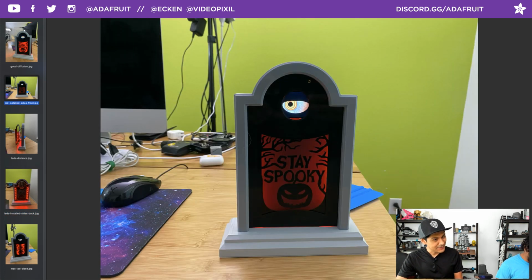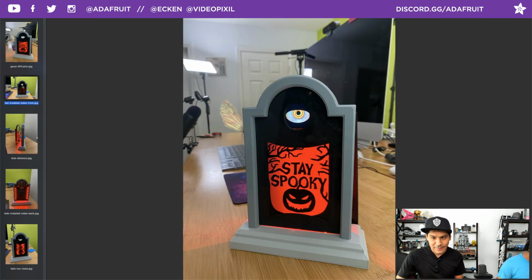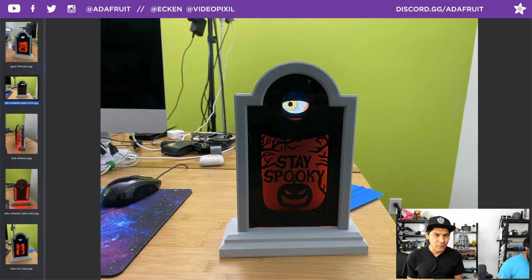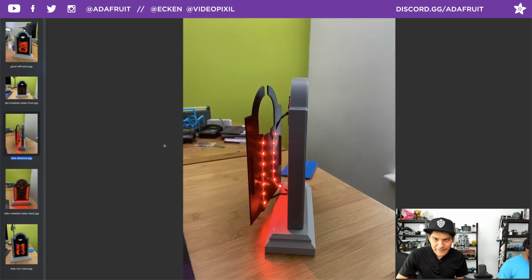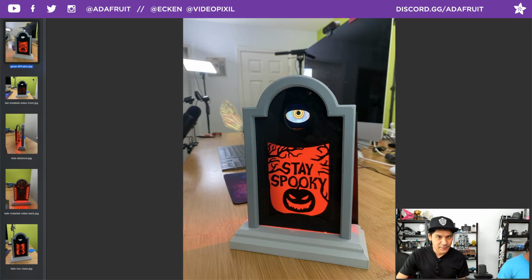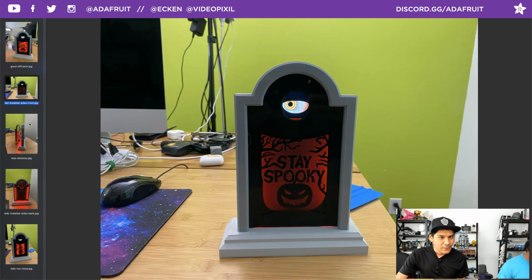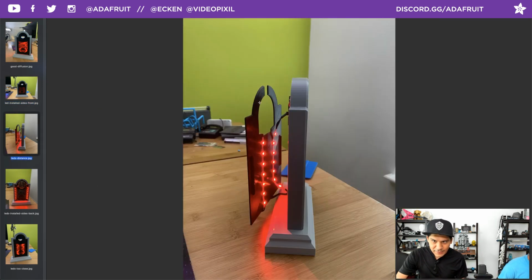It's very, very dim. That is an okay effect, but when you look at this and then at this, it's not an angle or camera shift. It's just the placement of the LEDs. Remember, when LEDs are positioned further away from your black LED acrylic, you get much better diffusion. So there's sort of a before and after, right? I had to go back to the drawing board and figure out how to get this thing to be that thick, right?